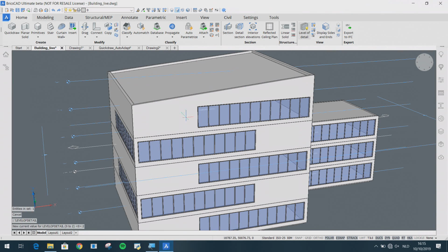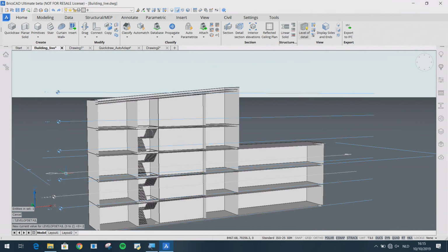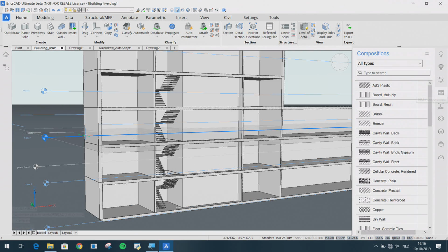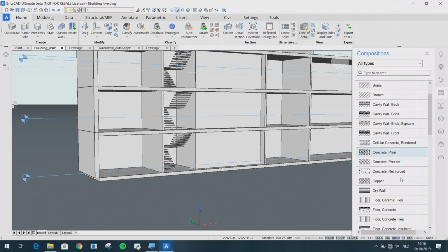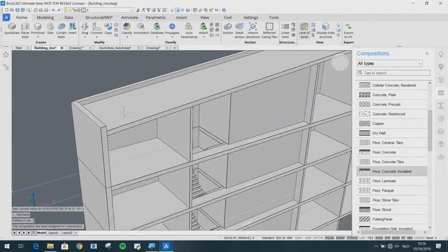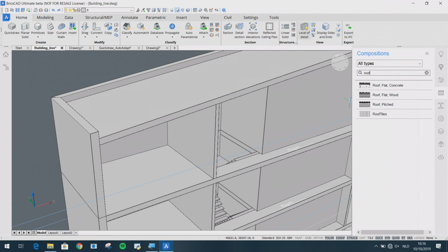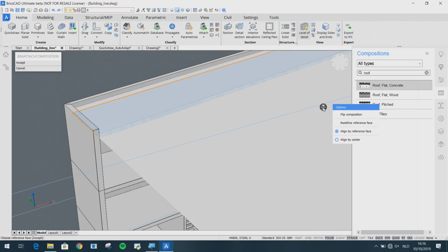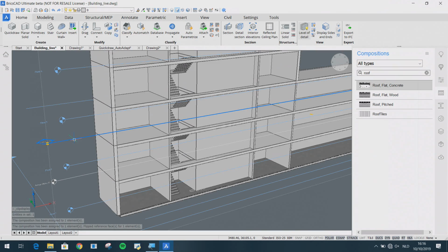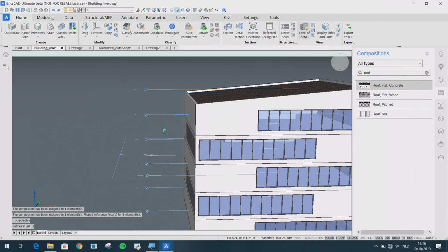So at this stage, everything is classified, but if you look at a section, you can see there's still BIM data to be added. The compositions still have to be in place. Also, window parameters are still at the defaults. There's some touching up to do. And until V19, this was still a manual process, not a difficult one. It's just going to the compositions panel, dragging and dropping some compositions on the correct entities. But there's still some manual work to make the correct selection sets and mainly to avoid forgetting something. So you have to make sure you cover everything.